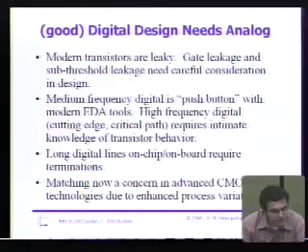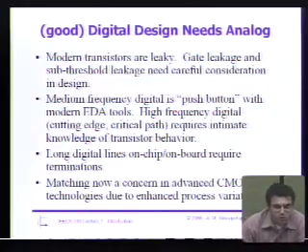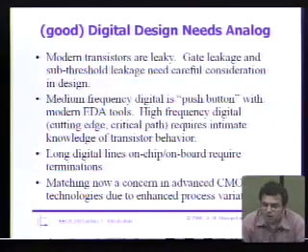I already mentioned this, I'll say it again: if you're designing digital circuits that have to drive anything off chip and your clock frequency is on the order of a gigahertz, you're going to have to know your transmission line theory. You're going to have to think about step response, ringing, all the good things that we talk about in this course and other courses are going to come into effect in those digital circuits.